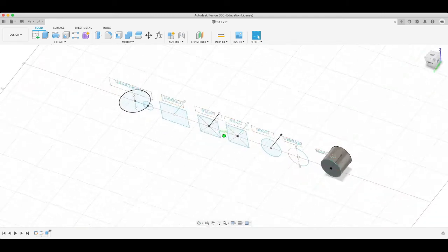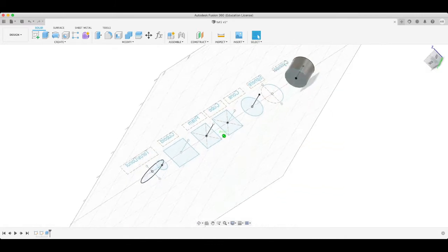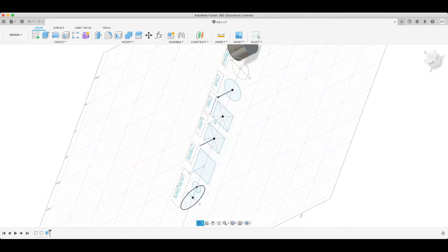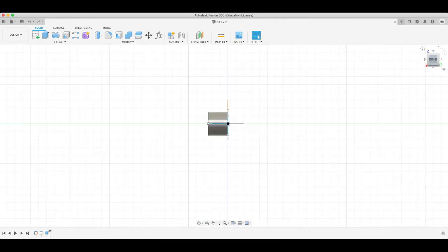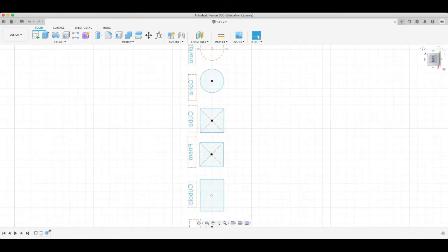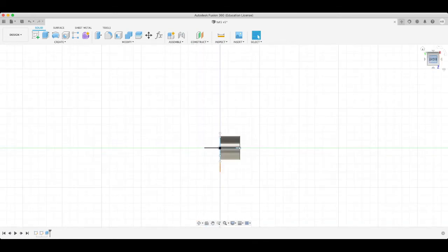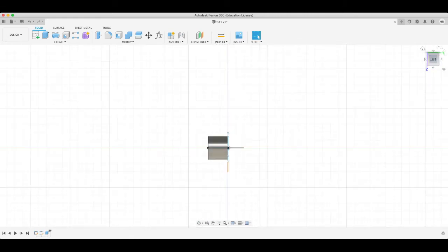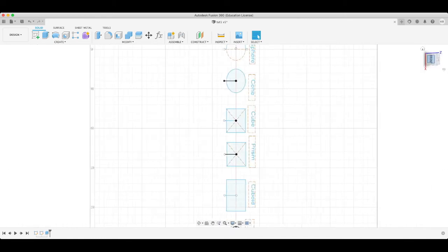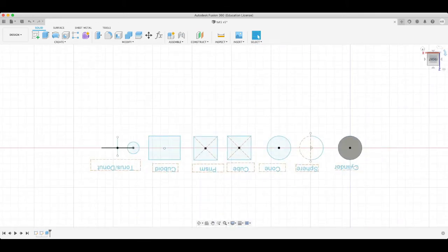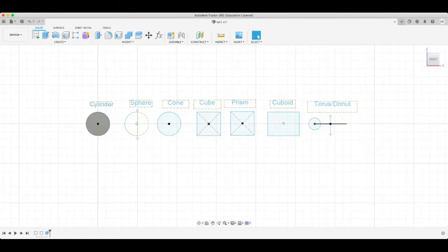So as you can see, I'm moving the navigation cube here. It moves the objects in the 3D planes. Yeah. So there is the right plane. On top of the right plane, we have the top plane, we have the back plane, the bottom plane, and the left plane. So we'll just be starting in the right plane. So just get back in the front. Okay, let us start in the front plane, since that is the plane in which we draw all the shapes. So just to orient it back, I rotate it a few steps, 2 degrees.